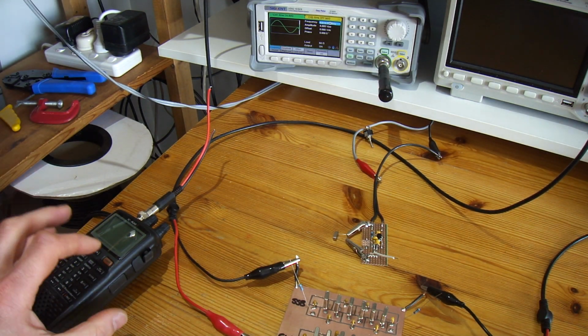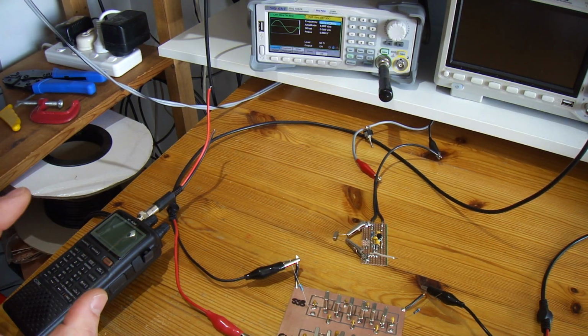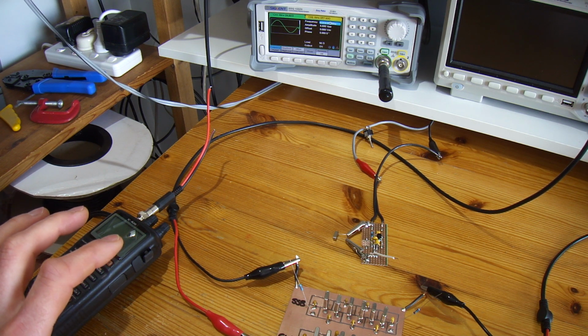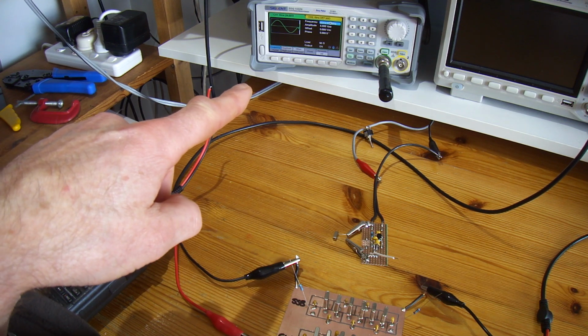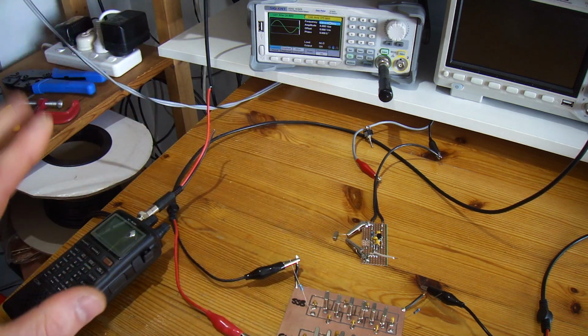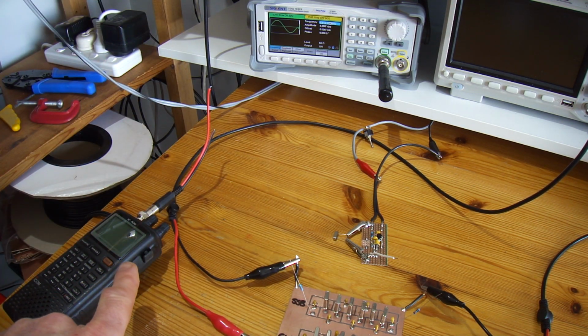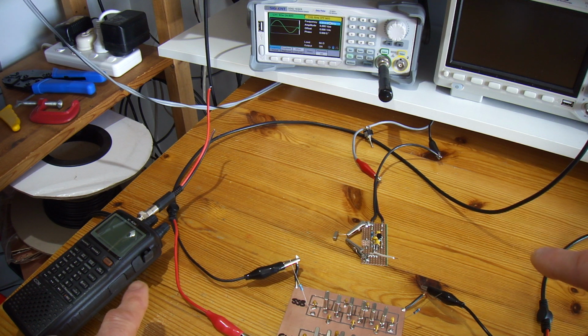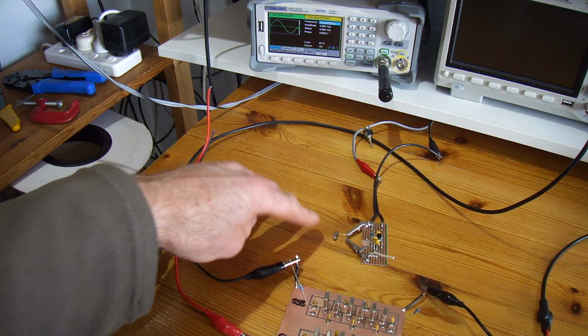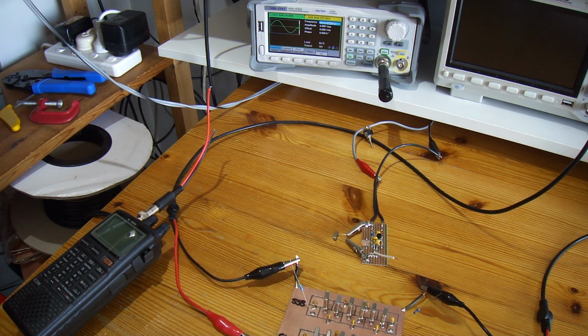So what I'll do is I'll just turn on the radio now, and it's probably going to be a bit loud, but you'll hear basically no beat, and then I'm just going to tune off the SIG-gen both above and below the crystal frequency, and you'll hear what I'm talking about. I normally do this with headphones on, and it's really clear in your head, and you can tune it up very quickly. I was getting down to around 1 every 20 seconds in terms of putting it in, let the temperature stabilize a bit, because you don't want to have too much heat on this, because that also varies the temperature, so again the frequency. But like I say, it worked out well.